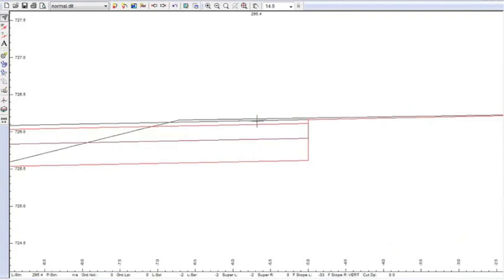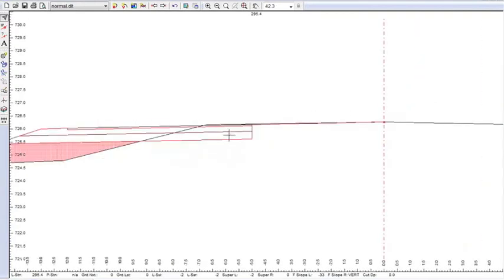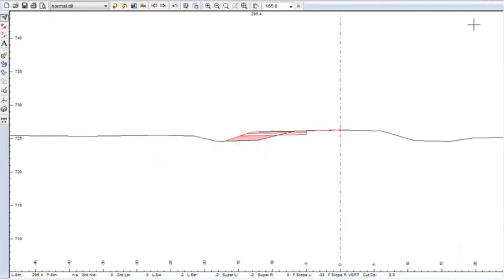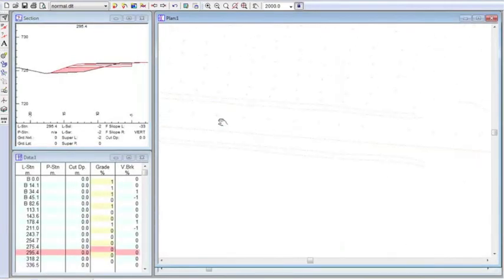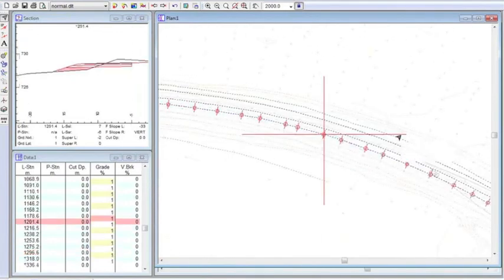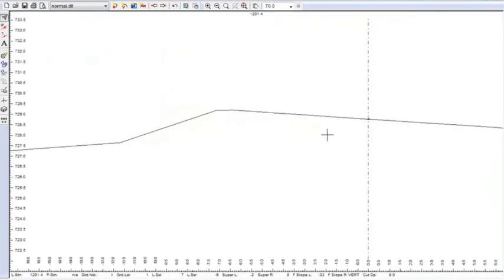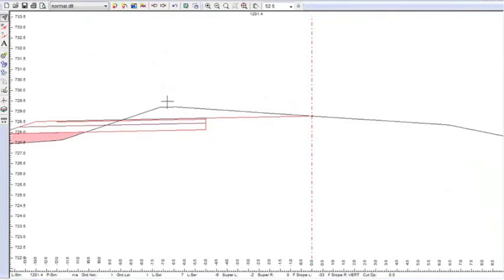It's not quite following the old roadway exactly. And if we get into the super elevation part, it's not doing a good job at all. Let's take a look at the curve. I'm just scrolling along here in the plan window, and aha, there's my curve. Let's take a look at a cross-section there, and you can see that the widening template is doing a very poor job of matching the existing alignment. It's cutting away all the old super elevated road and making it flat. Well, this could be a real problem. Changing the super elevation of the widening template to match the old road would take an awful lot of overrides, and it would be a painfully trial and error process.